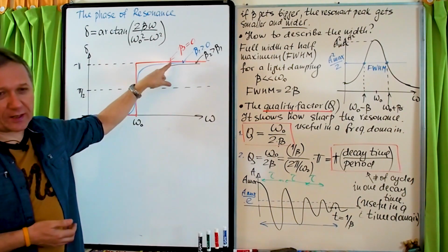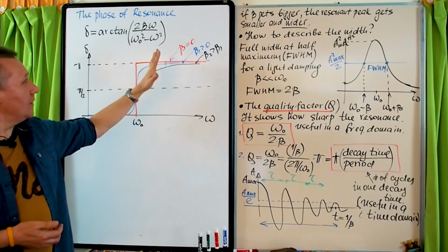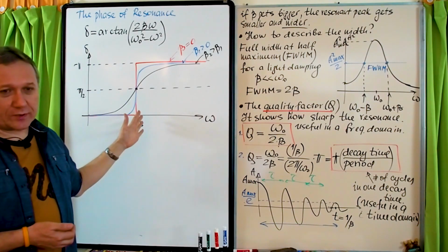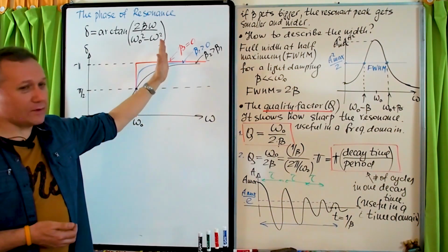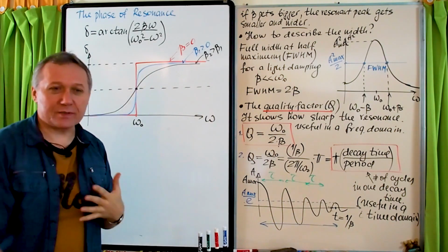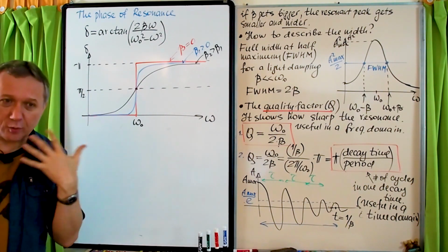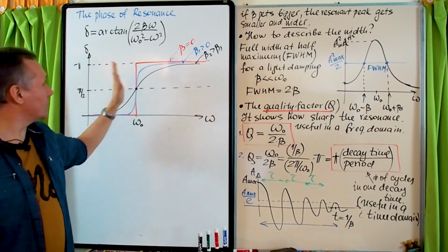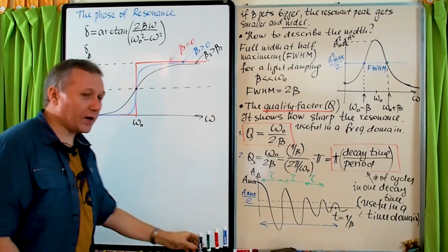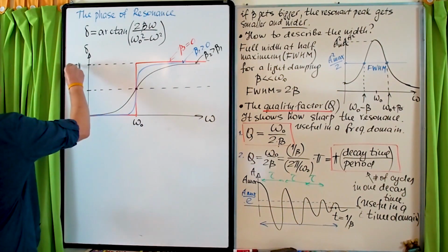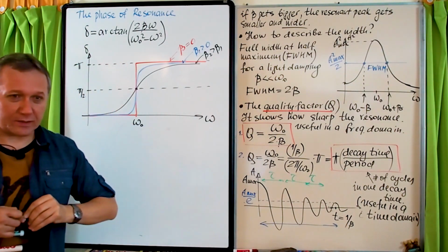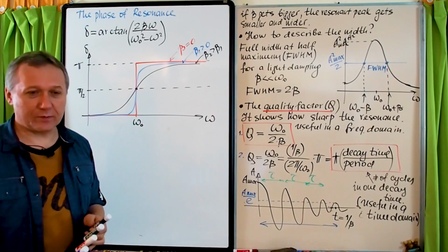We had to take into account where most of the noise is and where the natural frequency is, because if the noise is larger and we need to compensate for it, then the system would respond with an additional phase difference of pi, and we would have to add that additional phase difference in the feedback loop.